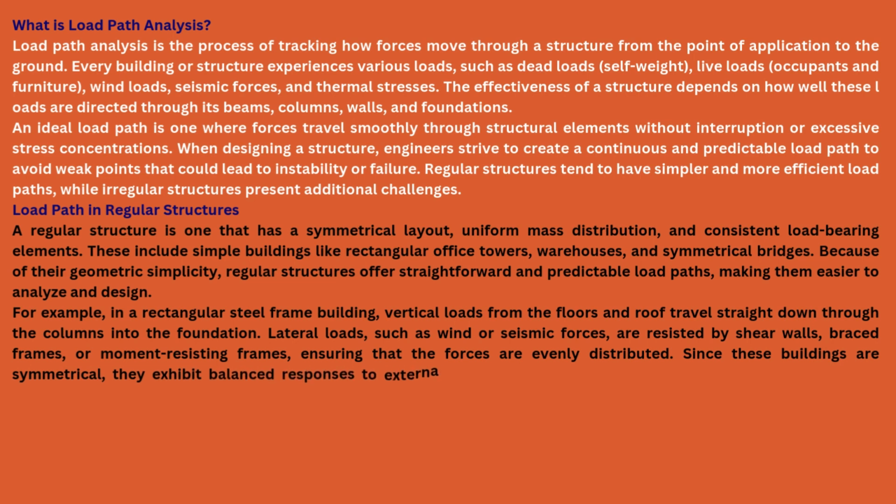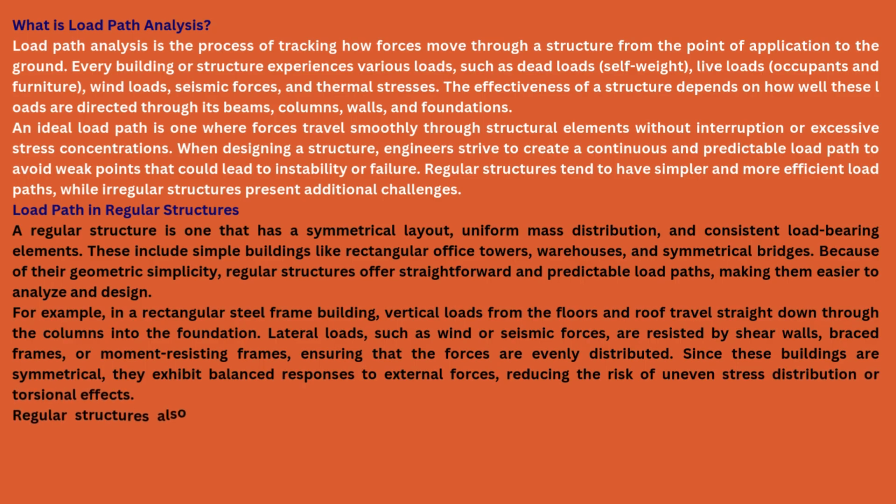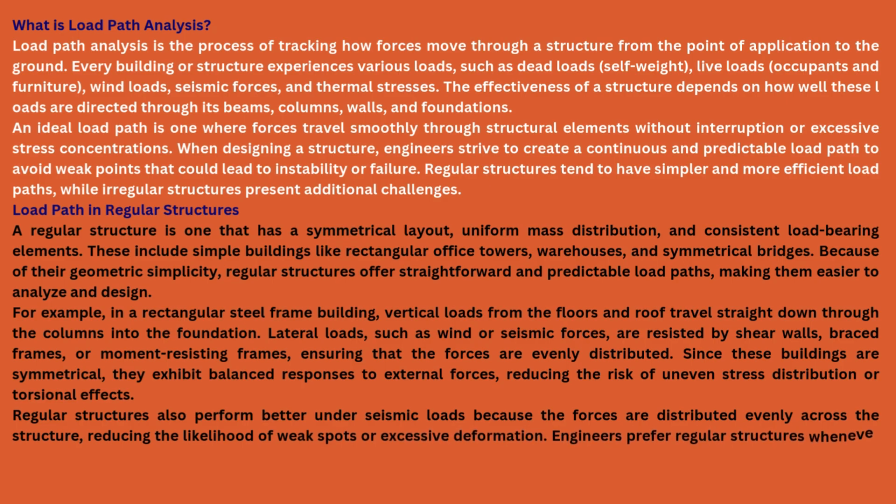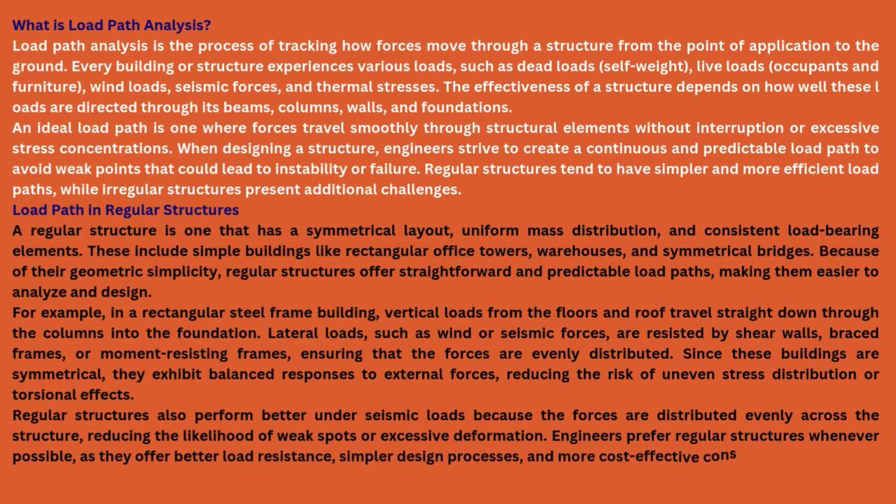Since these buildings are symmetrical, they exhibit balanced responses to external forces, reducing the risk of uneven stress distribution or torsional effects. Regular structures also perform better under seismic loads because the forces are distributed evenly across the structure, reducing the likelihood of weak spots or excessive deformation. Engineers prefer regular structures whenever possible as they offer better load resistance, simpler design processes, and more cost-effective construction.